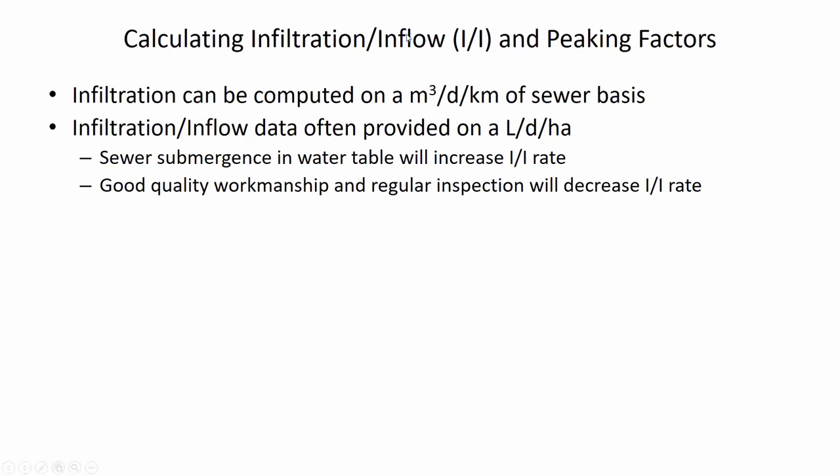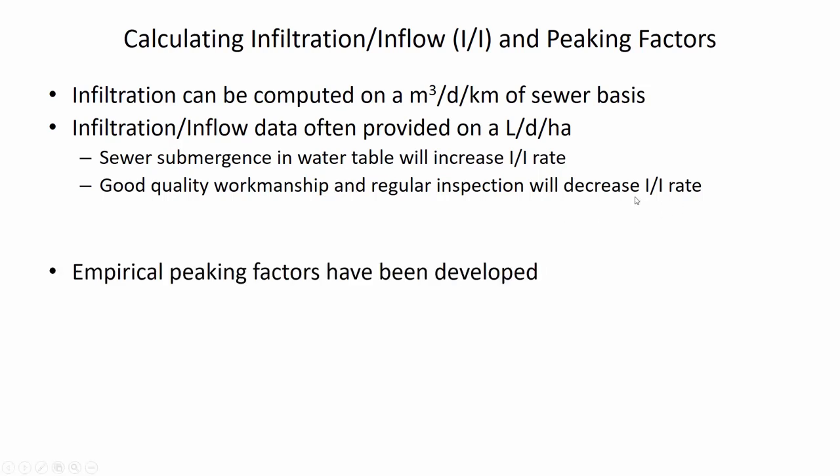Now, infiltration and inflow, remember those flows that are related to cracked pipes and wet weather. Having an effective inspection system, making sure that the pipes are laid on good subgrade base with good workmanship, and making sure that they are inspected regularly and repairing the cracked sections will decrease how much I&I there is.